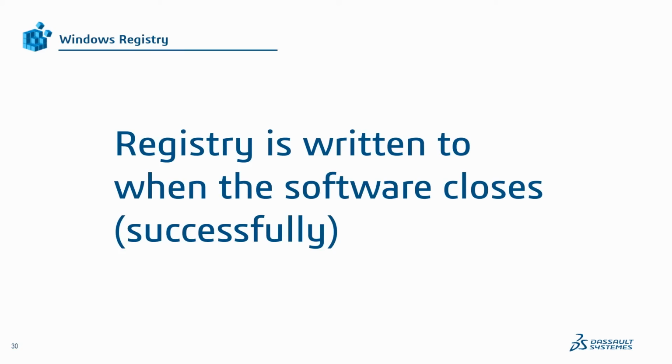This is something that I actually want to give a shout out to the SolidWorks team for, because it doesn't seem like it's happening anymore in 2020. I was going to show you guys a cool example, and I couldn't get it to happen anymore. But it is something that has happened in the past. Or if you get settings from someone else, you can copy their settings using Copy Settings Wizard. They could maybe be pointing to folders that you don't have, and that can be a problem. So being able to clear the registry is really helpful.